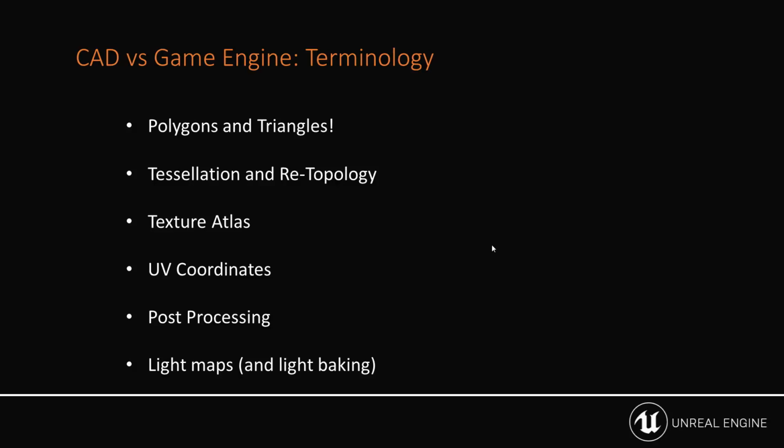This is especially useful if you're going to take your CAD design and turn it into almost a playable interactive visualization, or for something like virtual reality where performance is key. This really helps by lowering any performance hits that lighting can provide. Lighting can be very intensive on performance, especially dynamic lighting with real-time shadows where the light is moving and the shadow is moving with it.